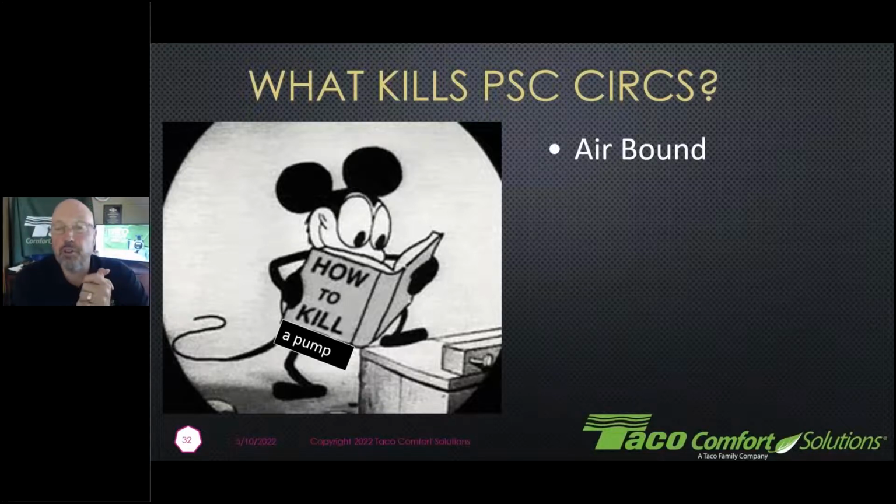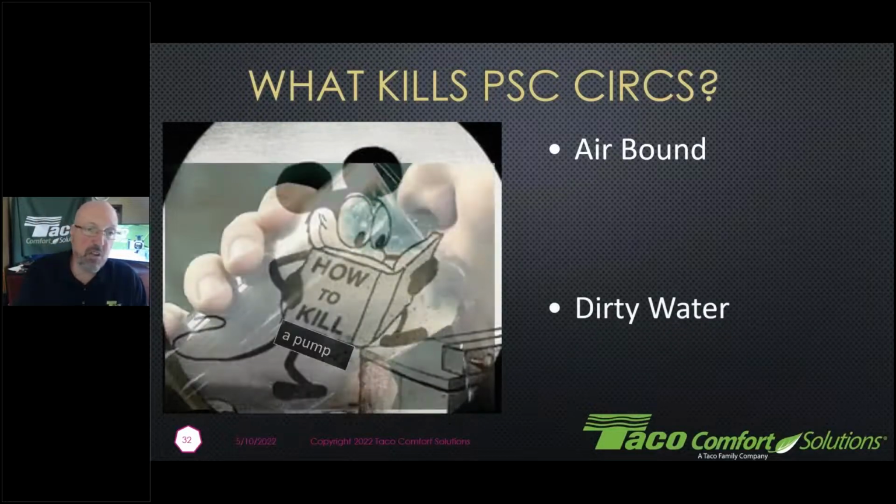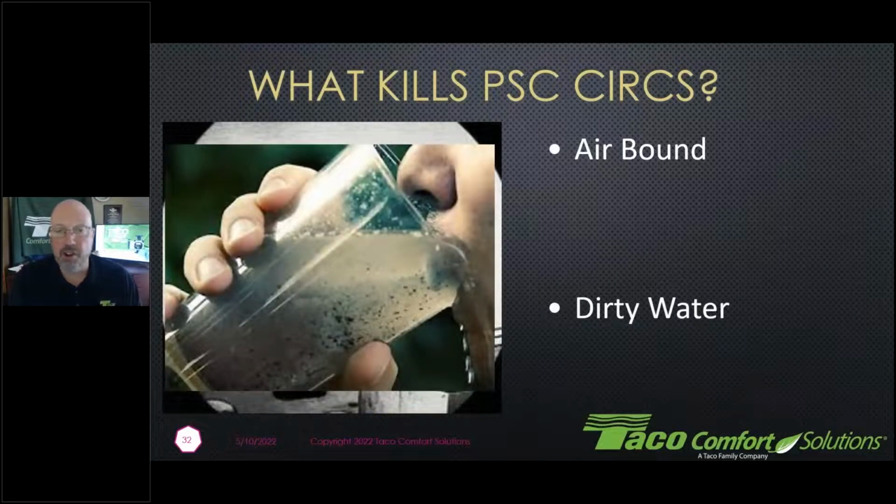So that's one big thing we hate in our circulators, having any air in our circulators. That will kill a circulator relatively quickly. The second way that's going to kill our circulators is dirty water.